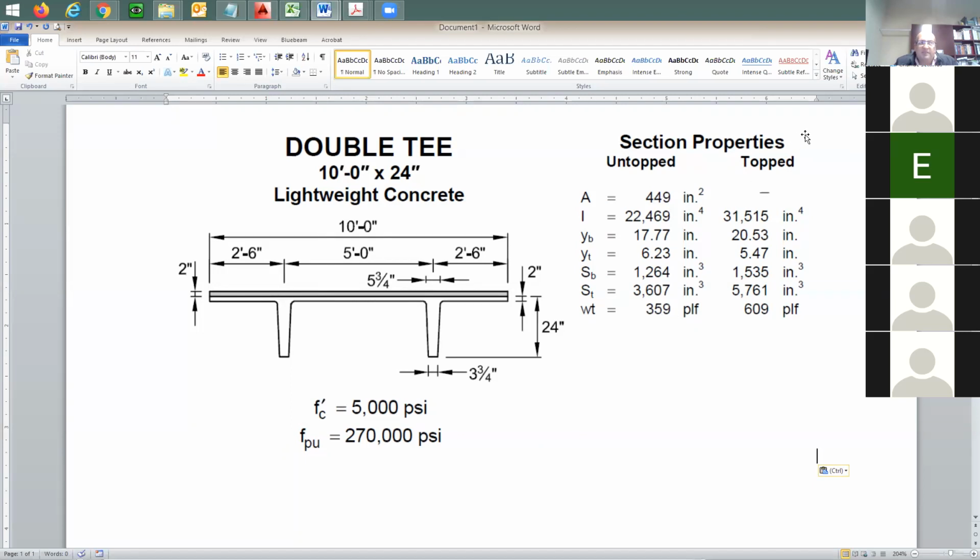Someone's going to say, how about these top properties? You can say, yeah, top properties, I guess I don't have the cross-section area for it. And this could be a big question mark here, right? Why don't they give me the cross-section area with the topping? I have the moment of inertia. And you see here it goes up with the top properties, right? Why is the bottom going to increase? Why is the top going to get reduced? Why? Because you are pushing the neutral axis up.